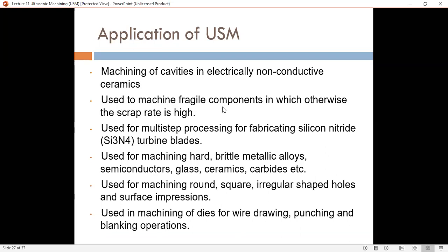The grit size is about 15 microns, and the indentations may be much less than that, maybe around 3 microns. Because of that, the mechanical force imparted on the workpiece per cut is very low.